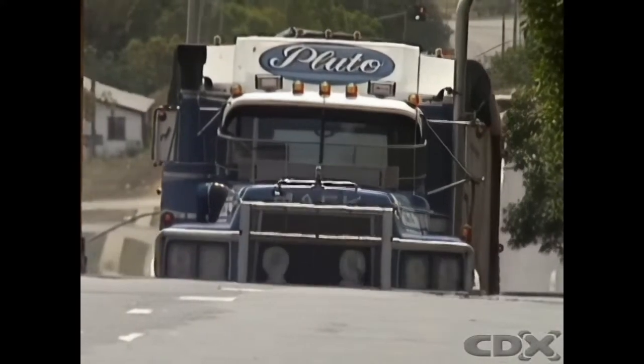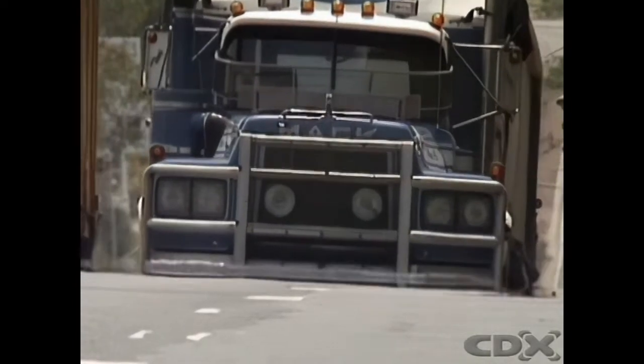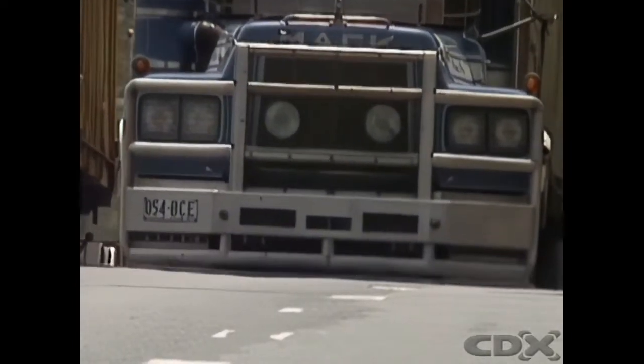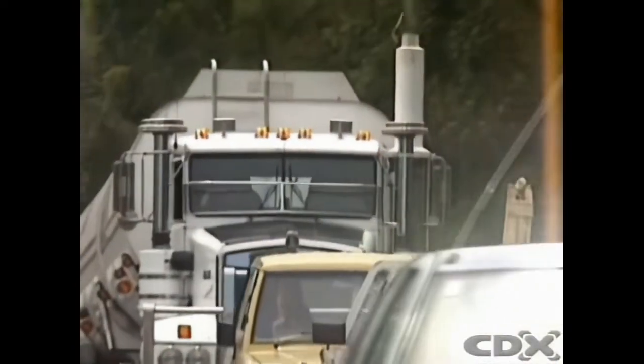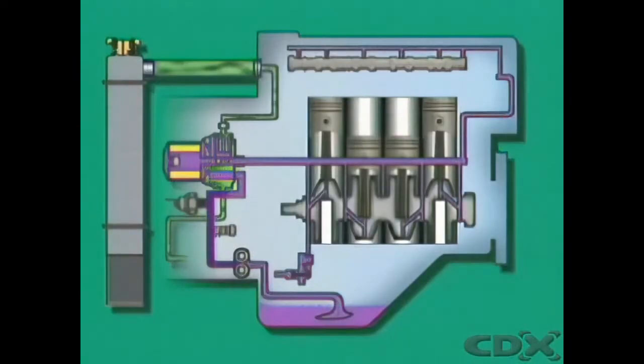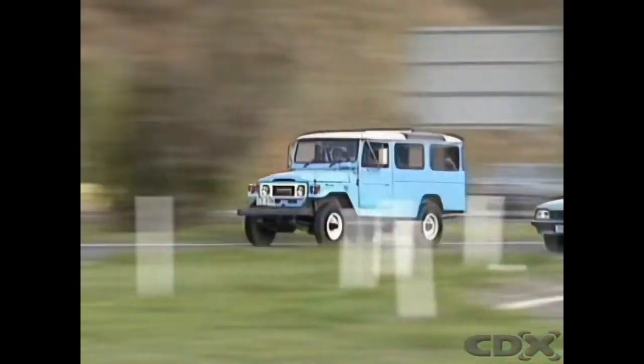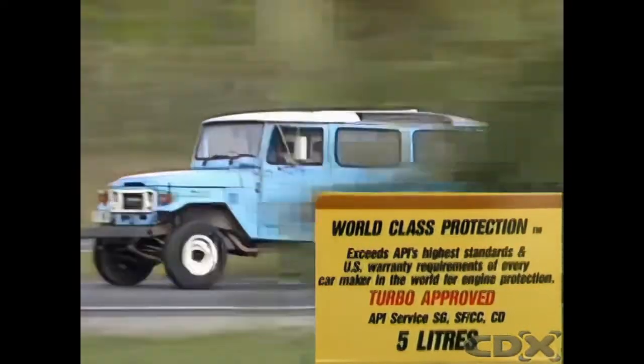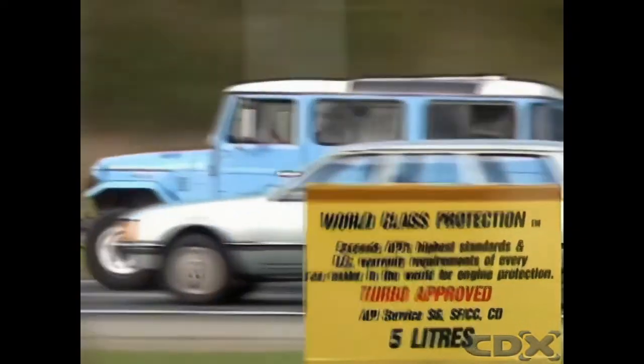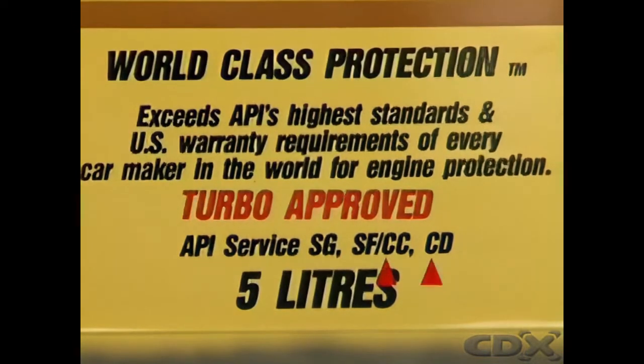Diesel engines are lubricated in much the same way as gasoline engines, but there are differences. Diesel engines typically operate at the top end of their power range, so their operating temperatures are usually higher than those in similar gasoline engines. So the parts in diesel engines are usually more stressed. As a result, diesel oils need a different range of properties and are classified differently.